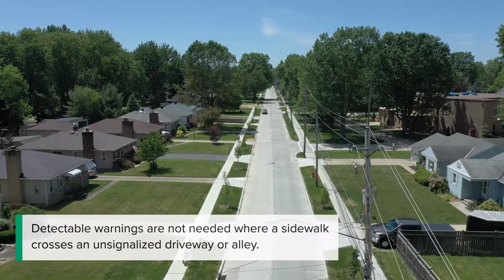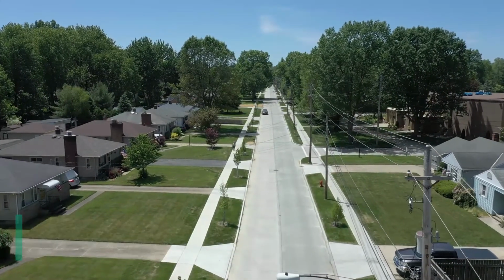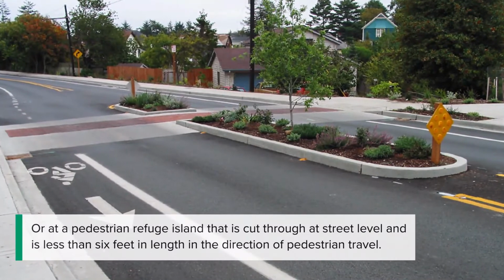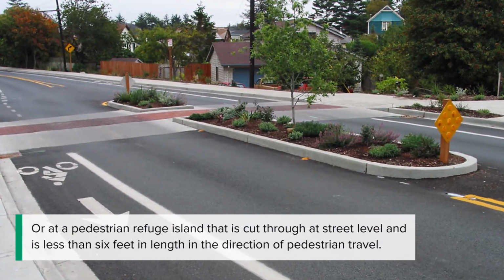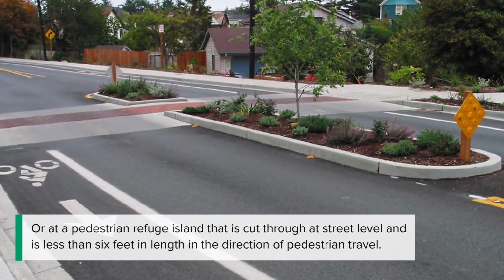Detectable warnings are not needed where a sidewalk crosses an unsignalized driveway or alley, or at a pedestrian refuge island that is cut through at street level and is less than 6 feet in length in the direction of pedestrian travel.